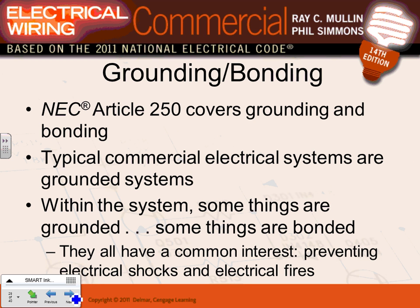Grounding and bonding. Okay, the system has to be grounded. I showed you guys how you ground the system by getting a Y, right? And you have to bond the neutral and the ground at the service, and you have to take the ground at the service and take it to Mother Earth through the grounding electrode conductor. That's all in Article 250. Any comments, any questions?